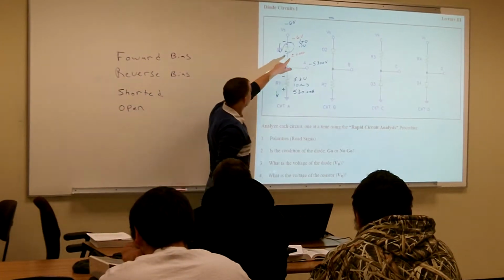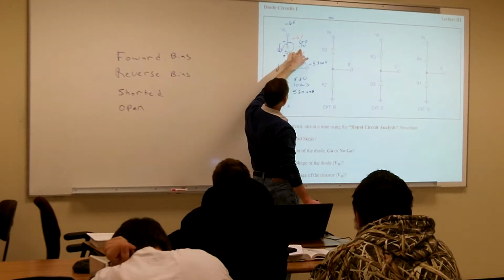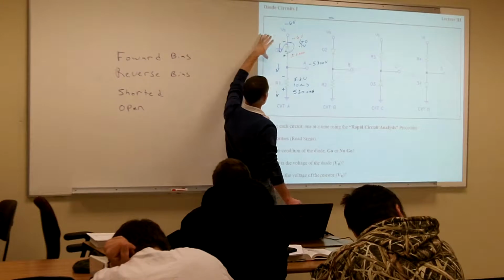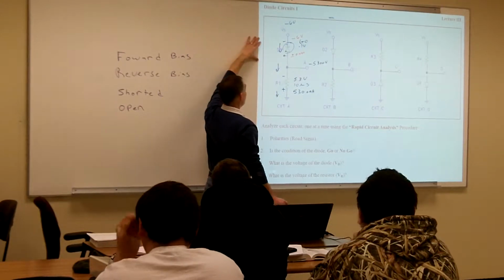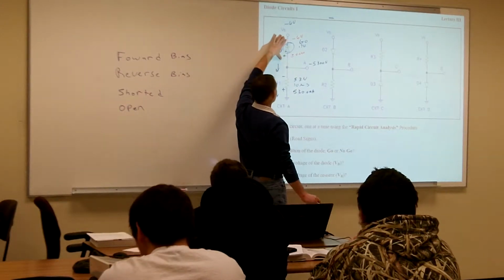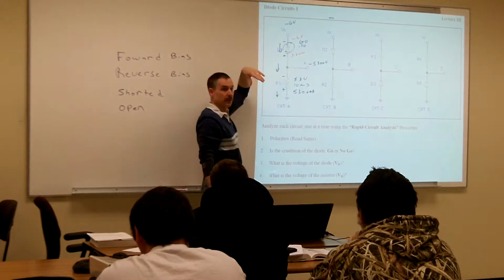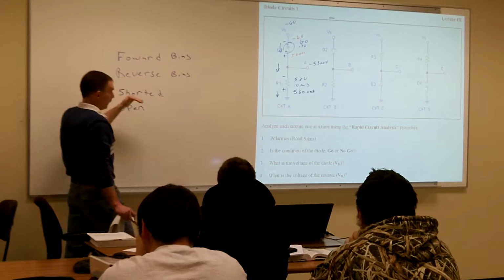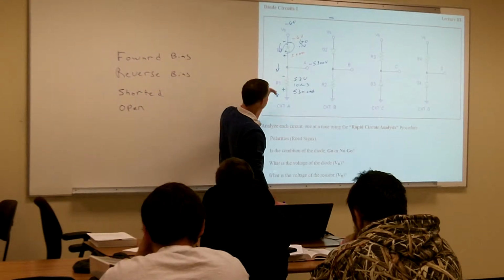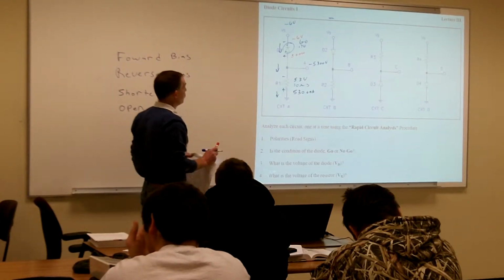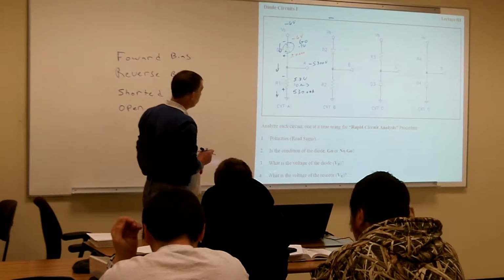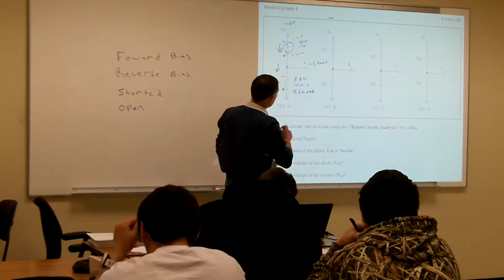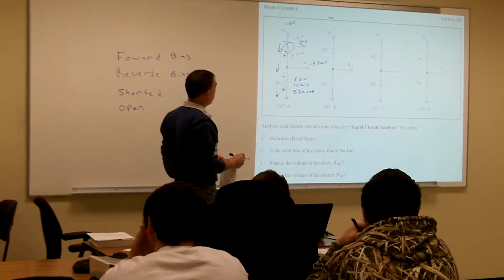Because no matter what, this diode is either going to want to drop 0.7 volts or the source voltage. So if I have a power supply of 5 volts and I just put it across that diode, it's still going to try dropping to 0.7 volts. So it's going to just act like a short across that power supply unless it has that current limiting resistor in there. It always just wants to drop that 0.7. That's all it wants to drop. Otherwise it acts like a short and it'll heat up pretty fast and ends up burning out.